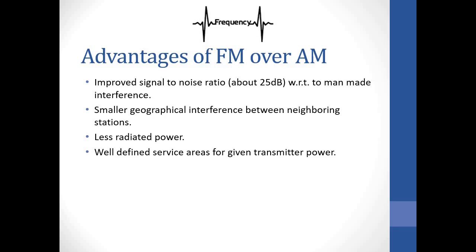So let's take, for example, we said that in AM, when it is modulated by several frequency components, like that of a voice band frequency, it produces several components also, which make up the upper and the lower sideband. These components vary in terms of amplitude in a complicated manner. Unlike in our frequency modulation, we know our power is constant. Therefore, with a constant power, we can actually map out the area to which that signal is going to transmit.